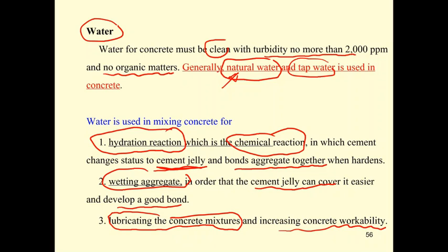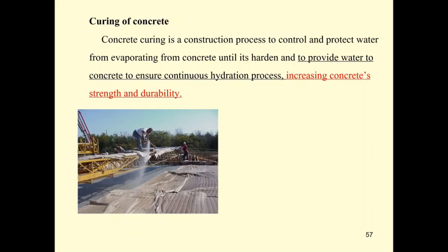If there is too little water, your concrete will be hard to compact, even if you use a vibrator. Nowadays there are additives that will help you increase the workability without putting more water into the concrete. The strength of concrete with this additive is going to be better than if you increase workability by putting more water into the concrete.